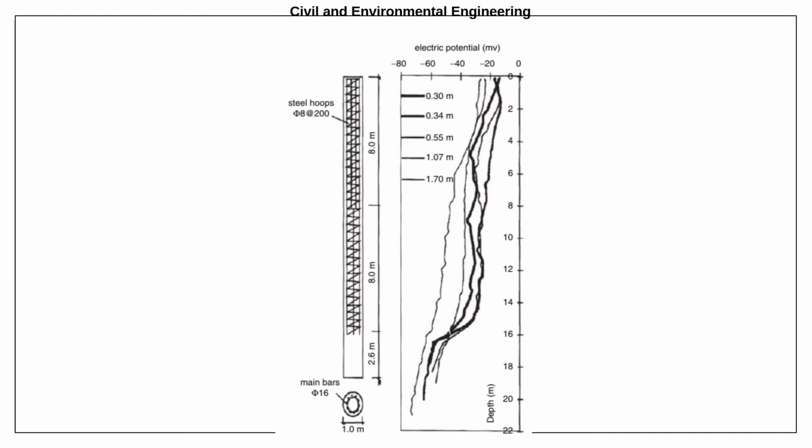Another example of resistivity is for construction. In here, they are using electric potential measurement in order to detect the presence of metal rebars within a concrete column. It's important for metal rebars to be present in the concrete column because they serve as reinforcement for your structure.